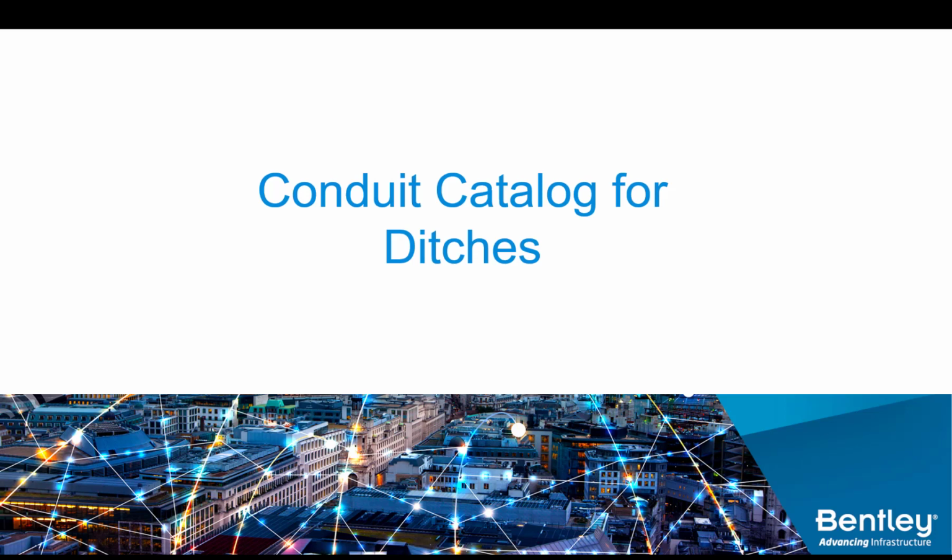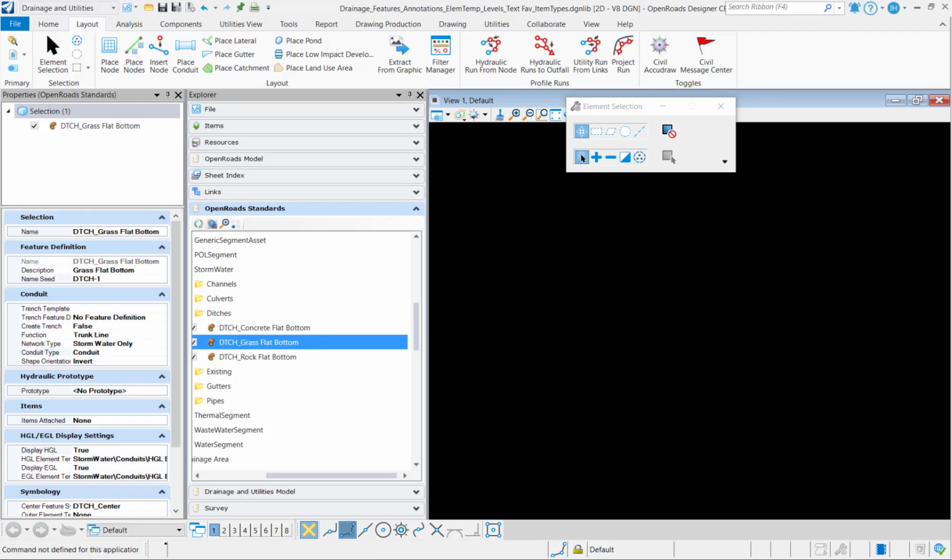This video will show the process of setting up the Conduit catalog for ditches. So here in the DGN lib for drainage, I'm going to take a look at my ditch feature definitions. I have currently one for a concrete, grass, and rock flat bottoms. So I'm going to have a catalog entry for each one of those.